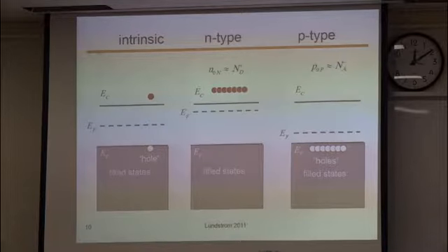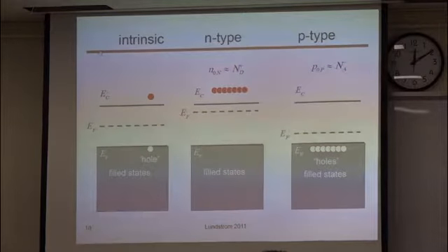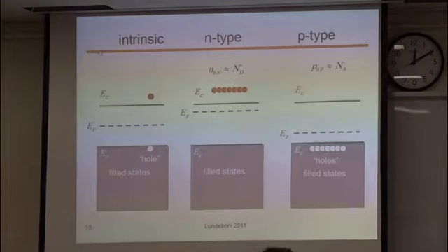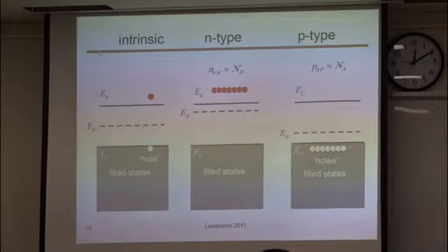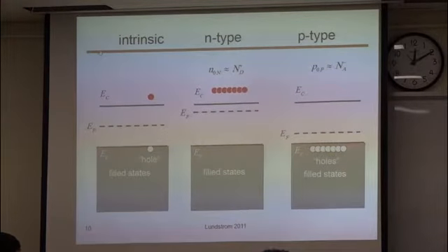Since the number of electrons is increased, the Fermi level will be increased, because the Fermi level defines the level at which we can find an electron with half probability. Since N-type has more electrons, the probability will be increased, and thereby EF, the Fermi level, will be increased.